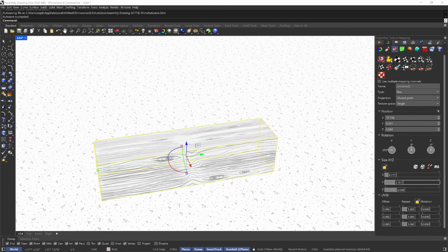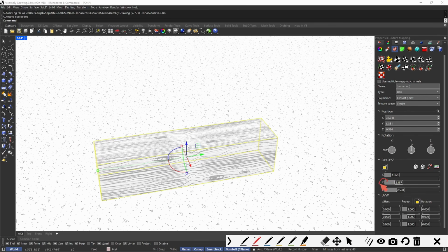This is the X axis, okay? So if I adjust the X axis, I'll show you. You see? Let me do this. So this is the Y axis right here. It's going to adjust any material that's perpendicular to the Y, okay? The X one, it's going to adjust any material perpendicular to the X in this orientation. And then the Z is going to adjust any material perpendicular to the Z axis, right? That's basically what it's doing, okay? So that's why you see them stretching in very specific orientations when I do that, okay?